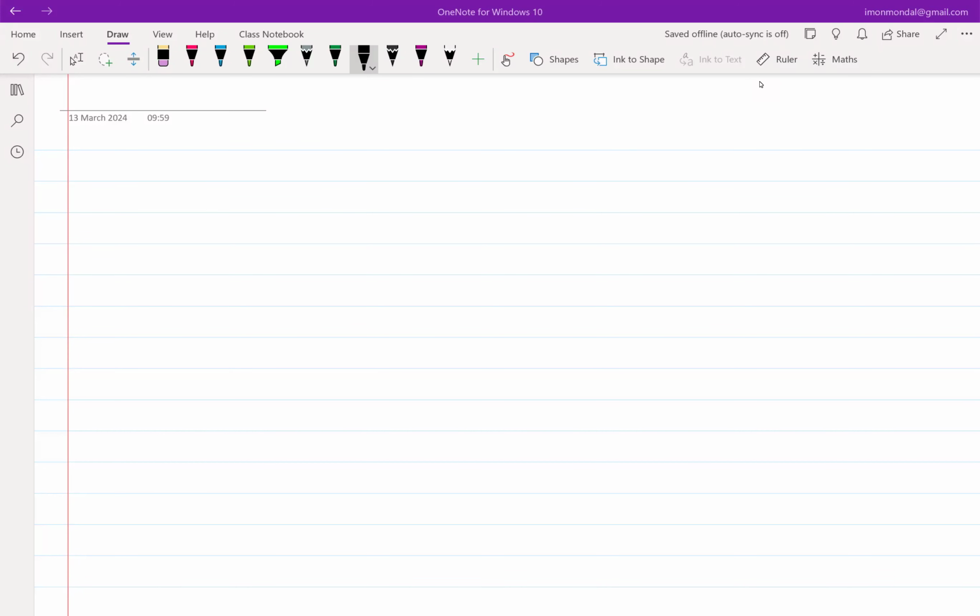Yeah, so we're discussing how to synthesize a voltage controlled voltage source. The discussion in the previous class was that there are four basic types of control sources: VCCS, VCVS, CCCS, and CCVS. We tried to characterize them with respect to the expected input and output impedances. If we form a table, this is what we should get.